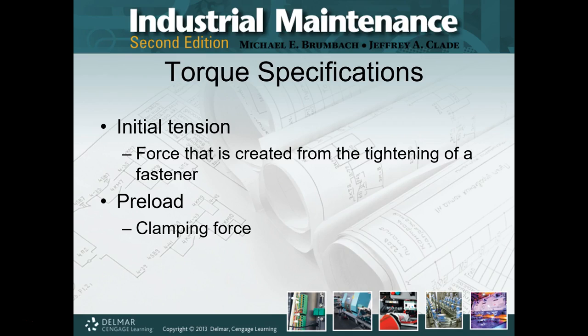Well, in this case, we're gonna heat it up to a particular temperature. And depending on the application, they will have a pyrometer. Think of a high temperature thermometer, and they will place it on the bolt to make sure it's at the proper temperature. Then they will take that bolt and insert it in the machinery, screw it down, turn it, tighten it, whatever,